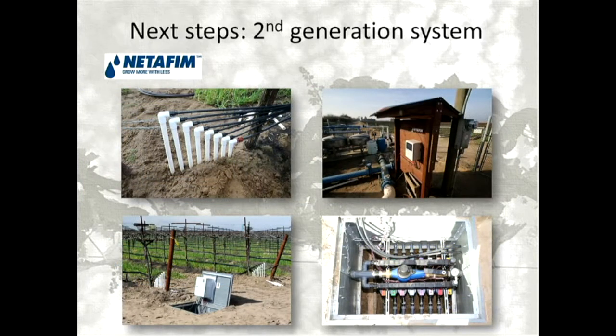This system we then installed in a 25-acre Malbec field in the Livingston area. The thought here is you put the box in, and each one of these valves will control green. Each one of these color-coded valves lines up with one of the colors. You can't see them here, but these lines are also color-coded. Each of these valves irrigates a 30-meter pixel. So we went away from the 15-meter pixel into a 30-meter zone, and each valve will control one zone. It's 20 vines wide and 9 vines tall.